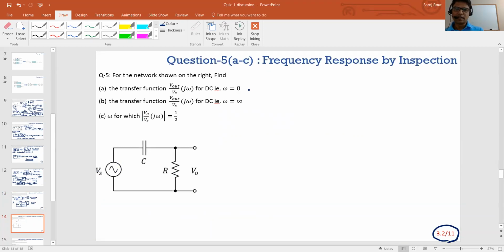Then if your circuit is not meeting a certain spec, you'll be able to fix that. So that was really the motivation behind this question: I wanted you to derive the Bode plot, just the magnitude, not the phase, as well as the closed form equation, without actually writing the node equations, okay? That's why I led you through these three parts. If I gave you this high pass filter and said find the transfer function, you obviously can write the equation, but usually you find the asymptotes. What I mean by asymptotes is basically these three questions.